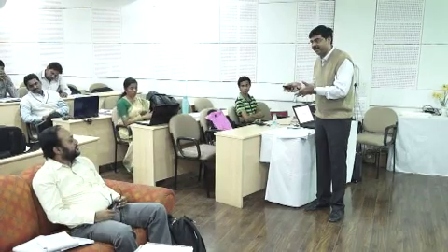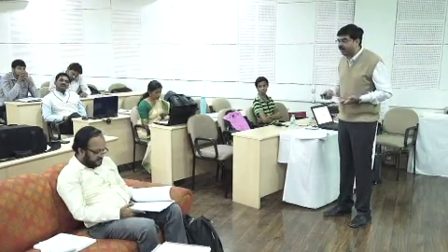Yes, sir. That's why I deliberately have a data set of inrush where the second harmonic is less, and a data set of faults where the second harmonic is more. I am not taking decision based on second harmonic; that is where my research focuses. For that, I have done the wavelet decomposition of the currents during various conditions, collected the statistical features, and using those statistical features, I am taking a decision. Okay, fine. Carry on.